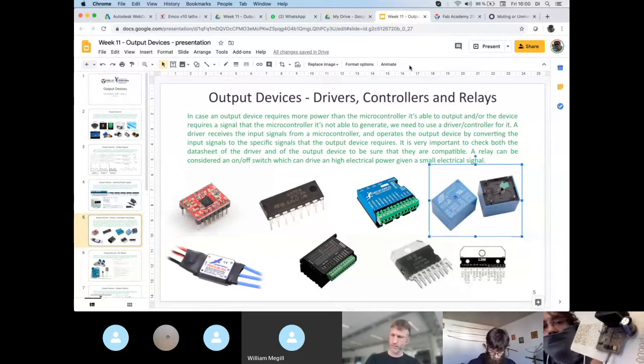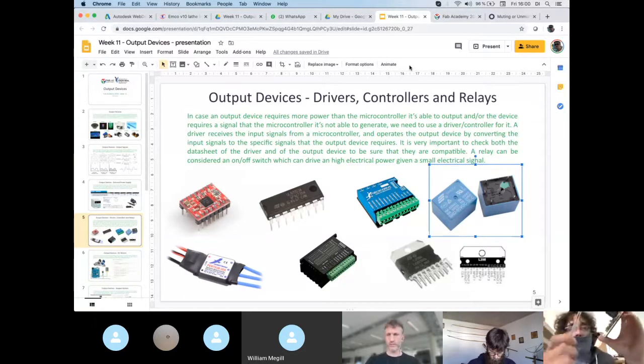So it's a way of letting the signal pass through, but never come back, with kilovolts of isolation. This is used, for example, when you have something on the other side, after the signal, that you need to control, that can explode or, I don't know, give you back a bad signal to the microcontroller.